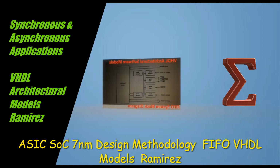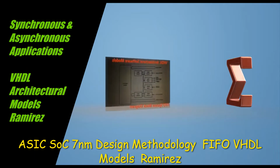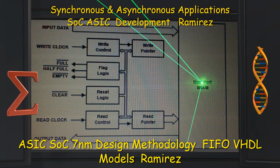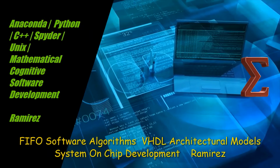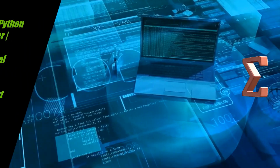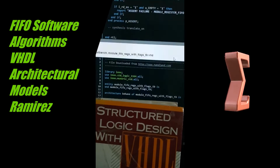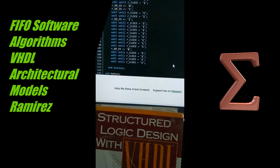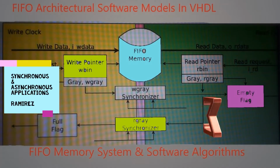The asynchronous FIFO, first in, first out memory device, refers to a FIFO design where data values are written to the FIFO buffer from one clock domain and the data values are read from the same FIFO buffer from another clock domain, where the two clock domains are asynchronous to each other.